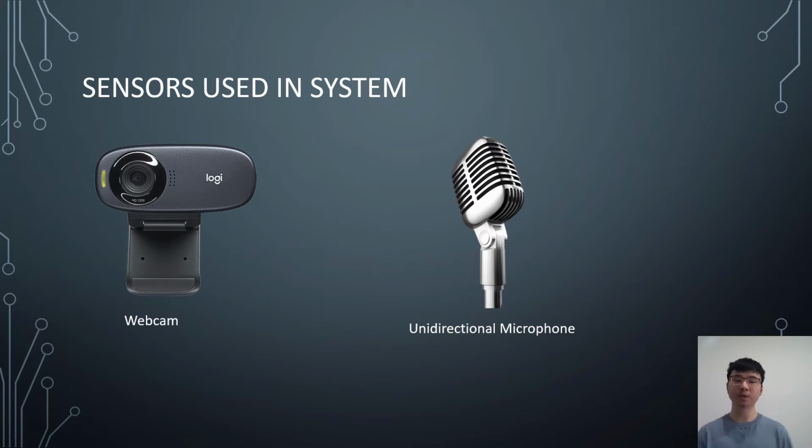The second sensor we will be using will be a microphone to determine the type of vehicle. The specific microphone we are using is a unidirectional type to mitigate the surrounding noise from the environment and isolate as much as possible the noise coming from each side of the road. In our analog electret microphone, the main sensing build is the diaphragm, which is composed of electret. Electret is a ferroelectric material that is permanently polarized.